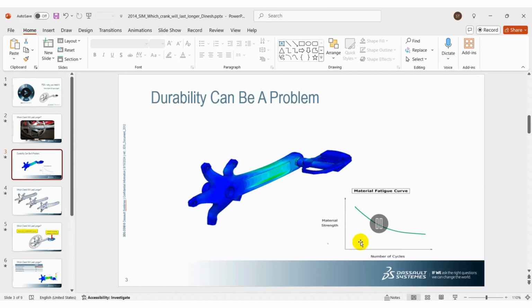So, material strength and the fatigue cycle. The material strength is a separate thing. If a material is sustaining a static load of something, the same cannot be applied to durability. 95% of the material failures in manufacturing sectors are due to fatigue failures. So you can't assess the same with what you do in static analysis using a yield strength, but you will be using the SN curve over here, and we will be assessing the failure of your particular part.